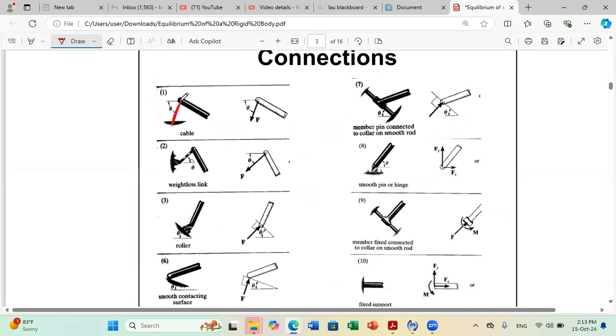That's why if I put a force on the body in a way to cause tension to the cable, by action reaction, the cable will develop a force opposing this action. So always, whenever you have a cable, the force of the cable on the object is from the object towards the cable, along the direction of the cable.